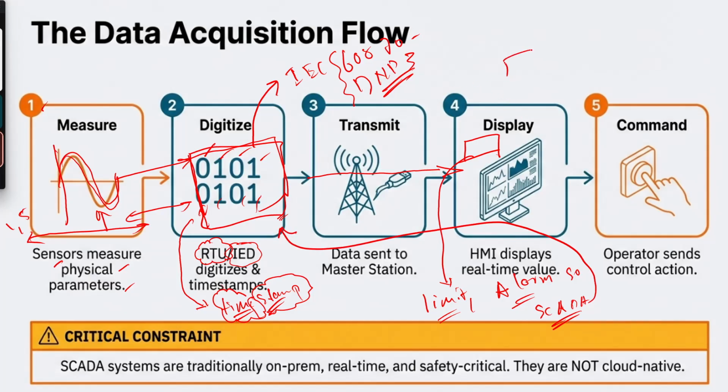If the packet equals the alarm state, the SCADA system will raise the flag telling that a specific device is in a not normal state, take an action. Okay, this is how the SCADA system will compare the set limit versus the actual data.